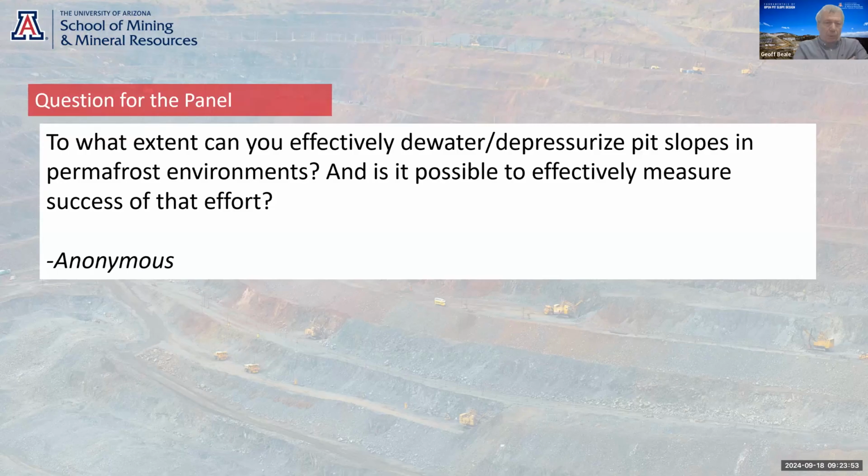problems with the slopes. It's normally quite easy. You just need to put in holes to depressurize the sub-permafrost environment. But that's something that always needs to be thought about. What happens when you get below the permafrost, and make sure that you've got enough drains in there so you don't mine into rock that's under excess pressure because of the confining nature of the permafrost.